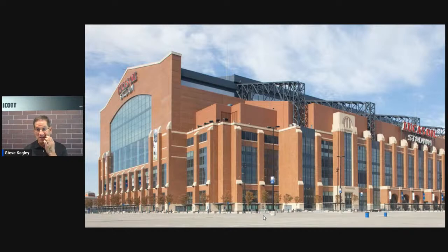But when you have a project like this, when you have a stadium that has over 1 million pieces of thin brick in it, especially in a panelized application like precast, you don't want to get a hot box or a hot spot where one panel looks completely different from everything else, because I can assure you that those brick are blended at the plants before you get them.